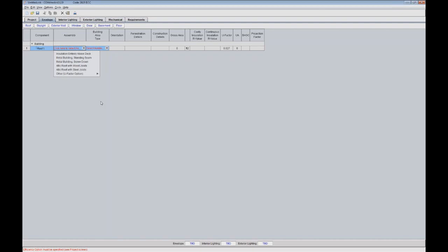So my next highly advised item is, as these codes become more complicated, and as we get into the 2015 and 90.1 2013, and how COMcheck works, which is really using the ASHRAE Appendix C methodology, a lot of it, and we use the lookup tables in the ASHRAE Appendix, I advise that you grab the current ASHRAE book or the code that you're working in.